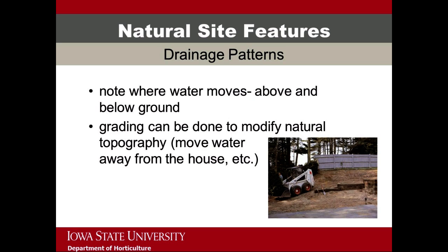Drainage patterns is another natural site feature. A designer should know where the water moves above and below ground. As mentioned in the previous slide, grading can be done to the natural topography to solve drainage problems when necessary. Moving water away from the house or other structures on the property is very important.